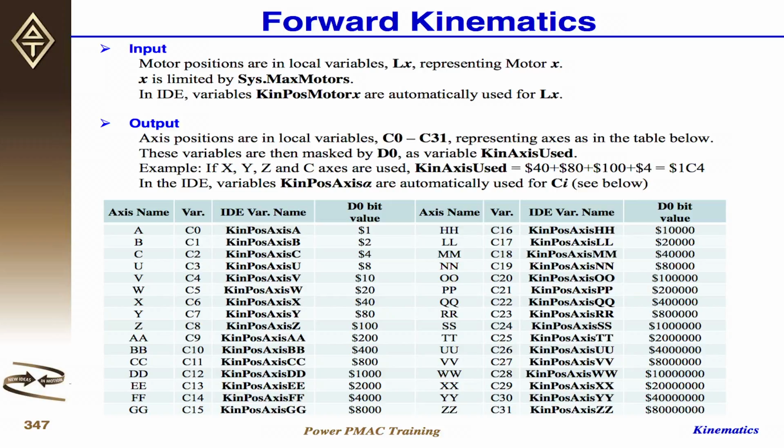This is in the motion program, that's abort. The other one is, if you are calling from the query command, then you're not executing anything, right? But if your motor is not homed, then that means your query will be wrong, because I cannot do the forward kinematics for you to do the calculation. So I send the illegal number, which is like square root of -1, which is not a number. Then I'll output that. Okay, these are the 2 statuses that we have. So this is just to prepare you for the template.